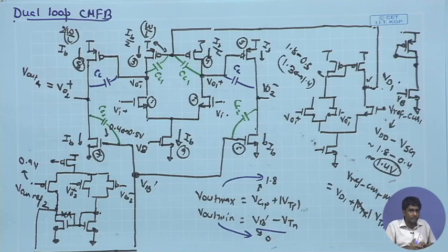So, that will be the main concern which will let us choose different values of CC, CC1, CC2. CC2 and CC1 can be close, because these two loops are common mode feedback loops and their speed of response demanded for a particular application may be close. CC can be different because the response sought by the differential loop can be faster.